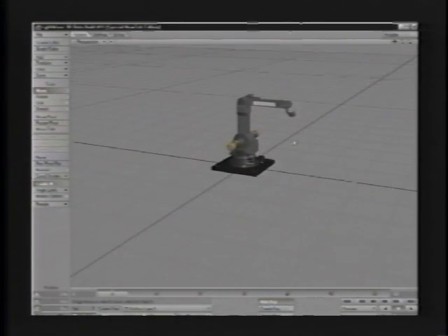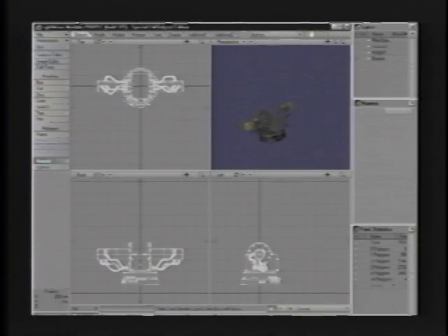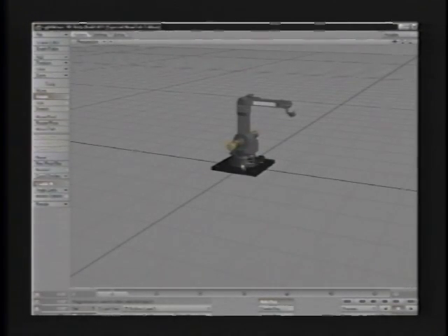You'll notice that the pivot point for this object here is still at the base of the object. The reason being, in Modeler, we determine our pivot point at the 0, 0, 0 axis. So you can see at this object level here, this is going to be our pivot point. Why is that bad? Well, let's take a look. If I go to rotate this in the animation, it's going to rotate around that point instead of around this joint here, and that, in fact, is very bad.